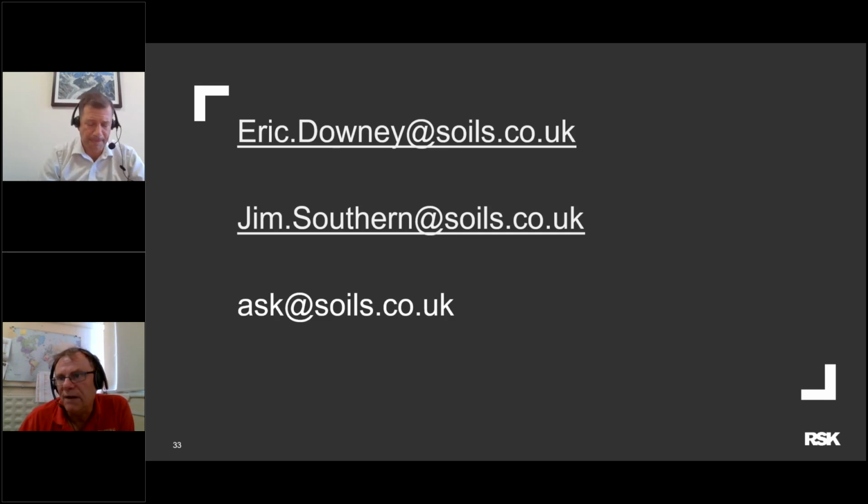What else have we got here then? What techniques would you recommend for rubbly ground conditions, such as the Cornbrash? Again, that is quite a tricky one. I would say, depending on how deep we're going, sonic with rotary follow-on is probably the most effective. You could try dynamic sampling, but you might struggle. But yeah, I would say sonic with the rotary follow-on.